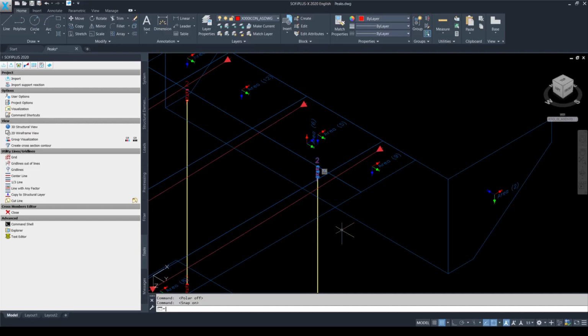Finally, the third location where problems can occur is at the intersection of the vertical column and the bridge deck. Usually the users define absolutely fixed or very rigid point-to-point constraints between the column head or column end and the bridge deck.